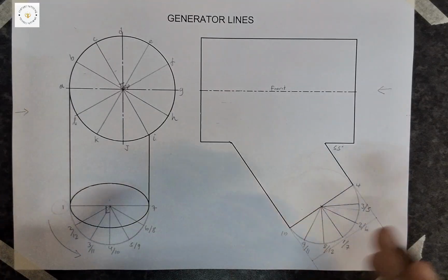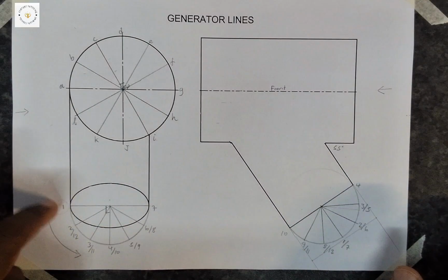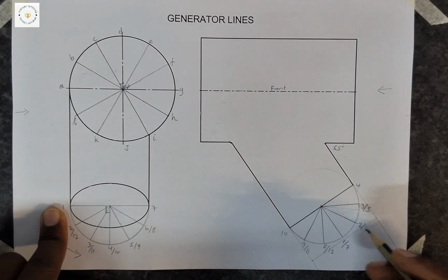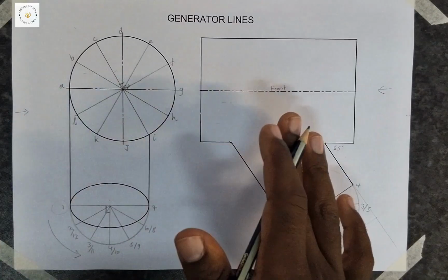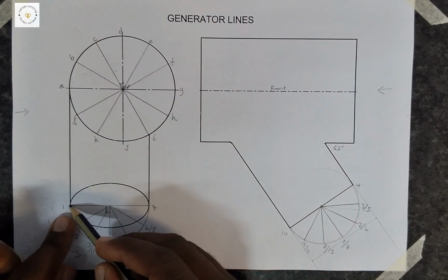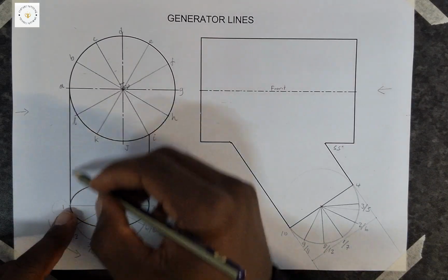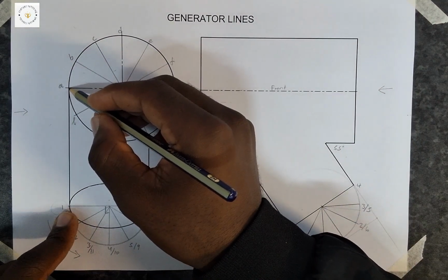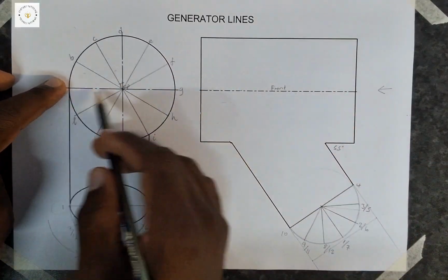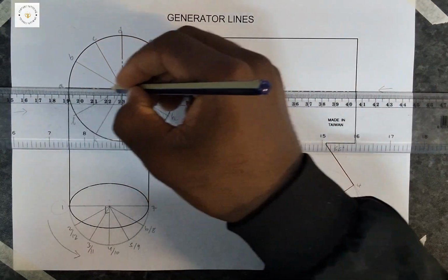What you usually want to do here is project your number from the top view to the corresponding number in the front view. Let's start with the one that's already drawn, 1. You see 1 is here at the right, at my left. If you project it, it goes to A, exactly at A. And then from A it goes up. So that is the line for it. I'm just going to project that line so that you have an idea.